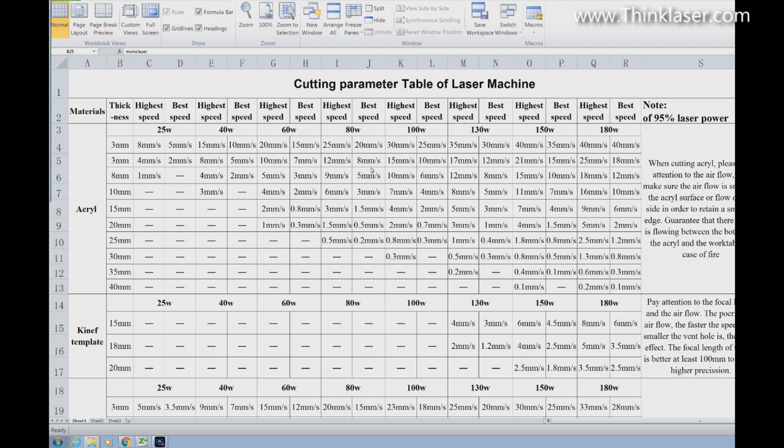When you're cutting thicker materials, the lens narrows the beam down to something called a focus point. If you're engraving, you need the focus point set to the surface. If you are cutting different thicknesses of material, you need the focal point set to different depths in the material to get the most efficient cut. I'm still trying to find out what KINF is, or KINF. Should that be knife? Just a bad spelling? As far as I can find out, KINF is a Russian oil plant.